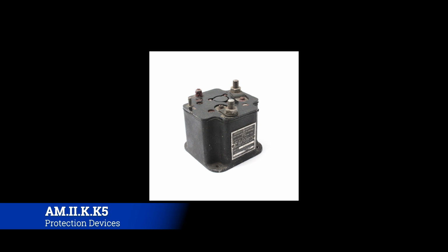Here's a reverse current relay. Most of these, where they're employed, have been integrated into the GCU, so you generally won't see them, but you could, especially if you're working on older aircraft, depending on where you go, because aviation's a wide world. Essentially, all these really do is detect that the current's going the wrong way, and it opens the circuit so that it can't flow back into the generator or into some place where you don't want it. This sort of methodology, even on 737s, is pretty common to be able to reverse current simply by opening and closing relays. So that's something you do want to get used to dealing with, and troubleshooting relays is a pretty viable skill for you.